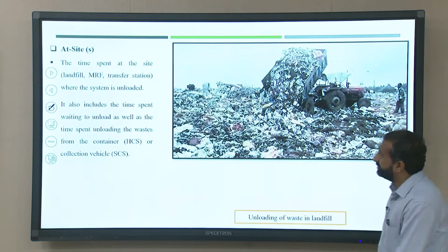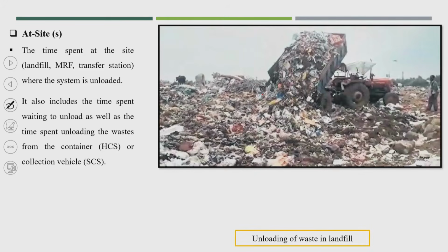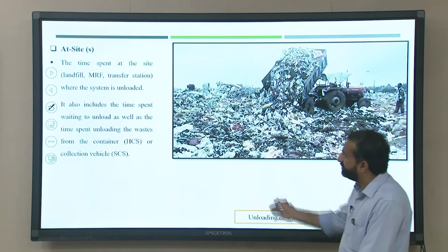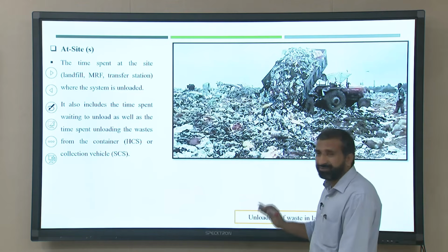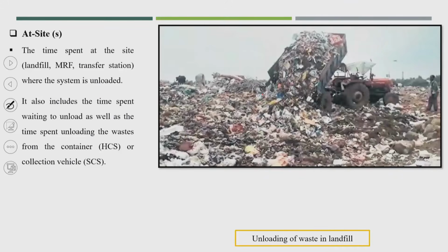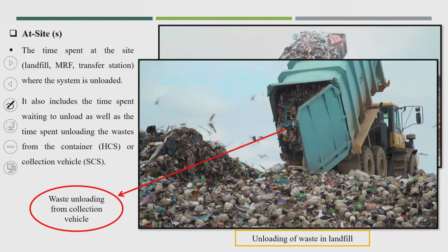Next is the at-site time. This is the time spent at the site, that is, the final place where the waste is disposed of. That could be a landfill, an MRF (material recovery facility), or a transfer station where the system is unloaded. That time also includes the time spent waiting to unload, as well as the time spent unloading the waste from the container or collection vehicle. In both cases, you see here, waste is being unloaded from the vehicle.